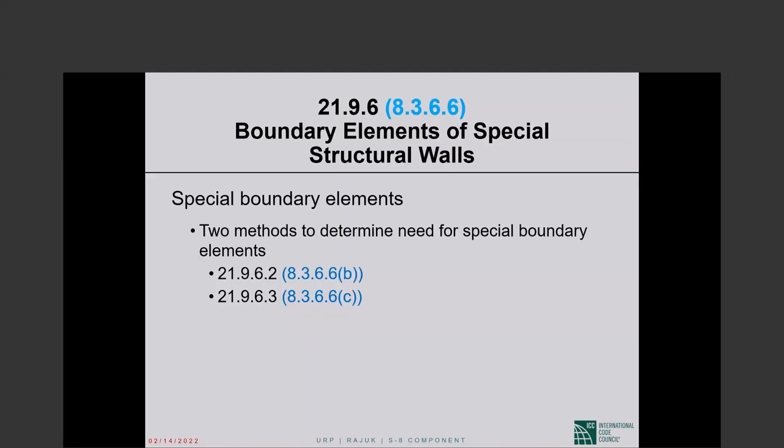There is a huge difference between a column and a shear wall. The difference is almost the entirety of a column cross-section has to be tightly confined. With the exception of a relatively thin cover, the entirety of a column cross-section has to be tightly confined.